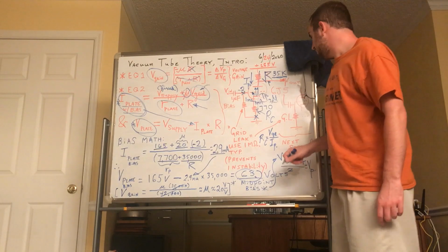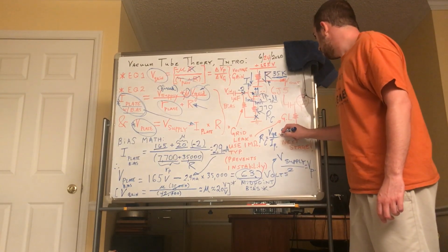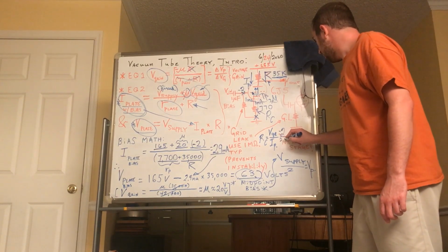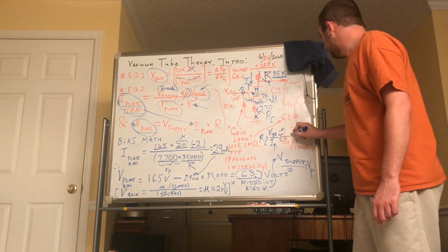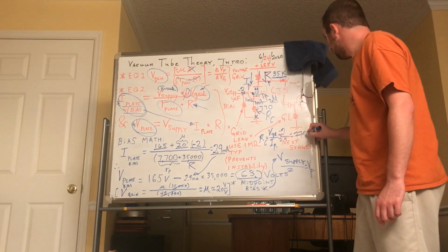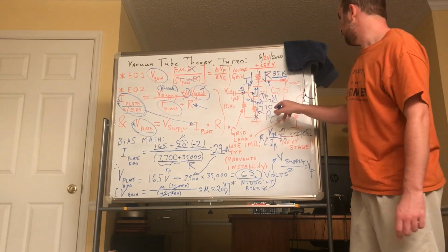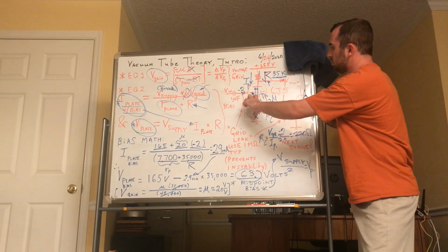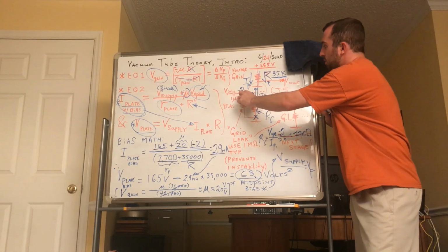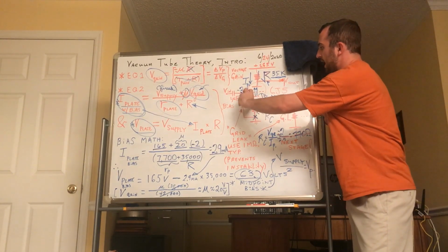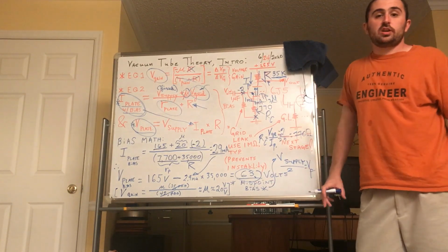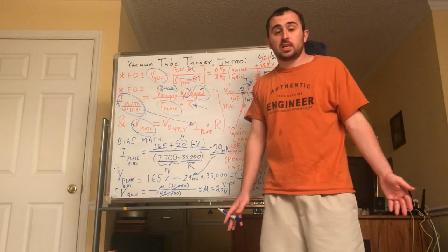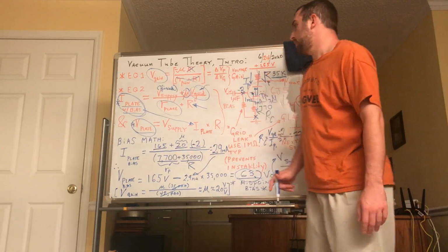And when you work the math, you would have 2 volts divided by 2.9 milliamps, and that would give you your 770 ohms, which is what's used there. And then what happens is the cathode is above ground by 2 volts. This is the cathode here. And the grid, because it doesn't draw any current, is at ground, so it acts as if there were that imaginary 2-volt battery. But nobody wants to go around having to replace amplifier batteries constantly. So this is why it was done this way.